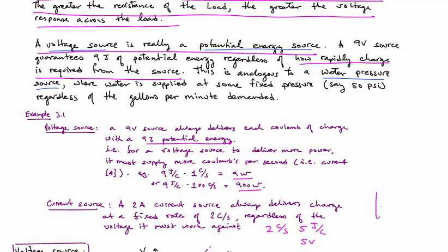So in other words, you have your current source here, that's 2 amps, and then you're going to deliver it into some load which is going to produce 5 volts. A 5/2 of an ohm resistor would do that, and that current going through there would produce 5 volts, such that now 5 volts times 2 is 10 watts. So that resistor would be receiving 10 watts.